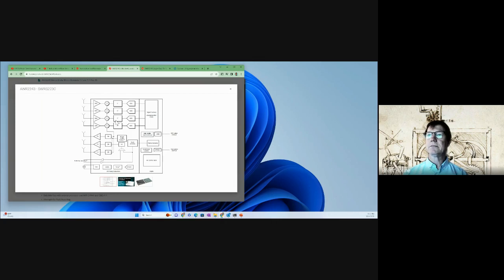So here, this is a little bit more your block diagram for the electronics hardware guys and gals. So we have some receive antennas here. We have 4 receive antennas, low noise amplifiers, these mixers to mix the transmitted chirp with the received chirp, right? And then that goes to an IF band.